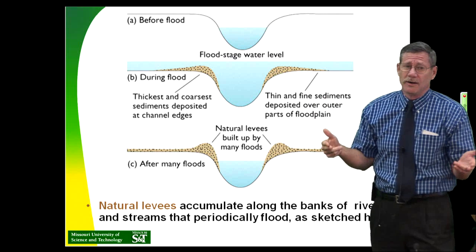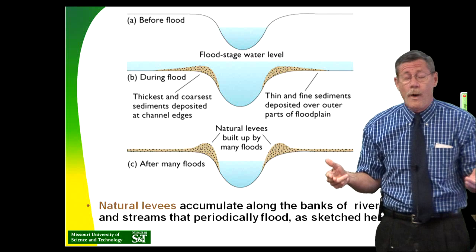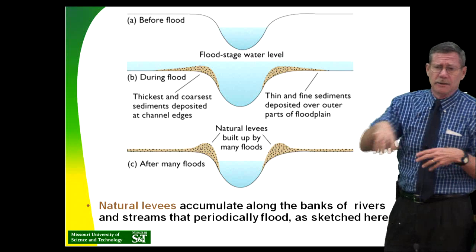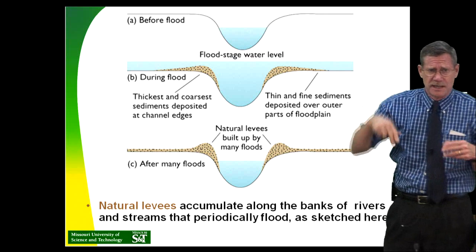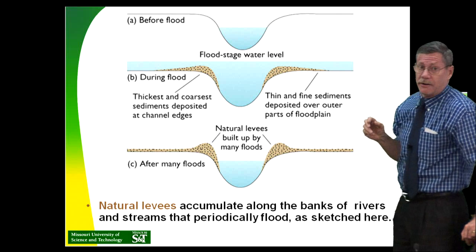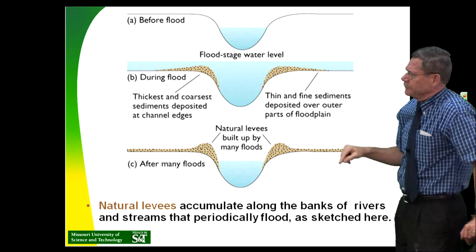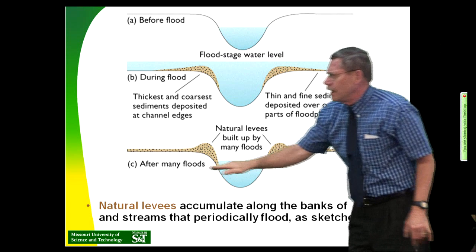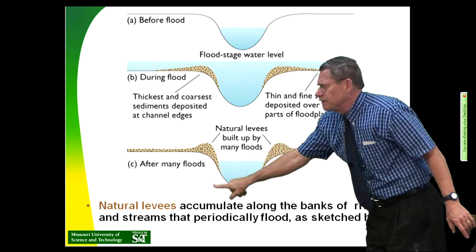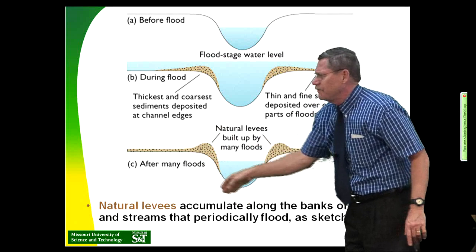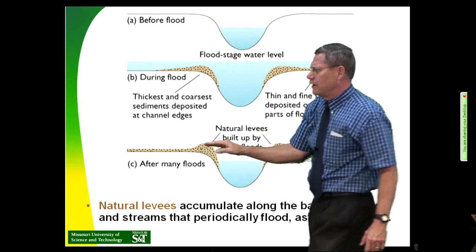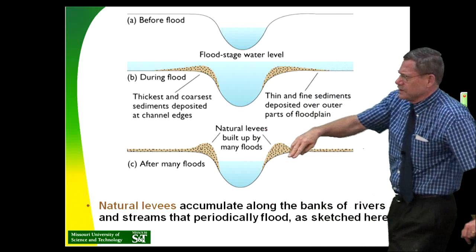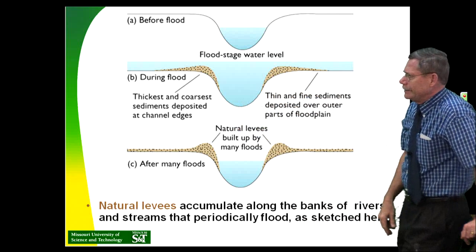You look at something like the Mississippi or the Danube River in Eastern Europe, wow, those systems are incredible for how dynamic they are, how much the channel can move around. One storm, the channel moves 10 miles across the floodplain. Wow, that's scary if you're the engineer, trying to save everybody. So this levees-only policy didn't work because of the curvature. And one side actually ends up being a lot steeper than the other side, and so that side fails through bank undercutting. You lose the levee here, and voila, the flood's all over one side of the floodplain pretty quickly. And because the river's so serpentine, it gets around to the other side as well.